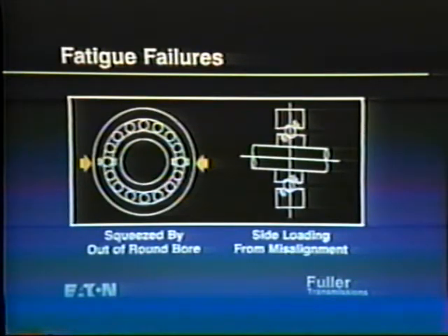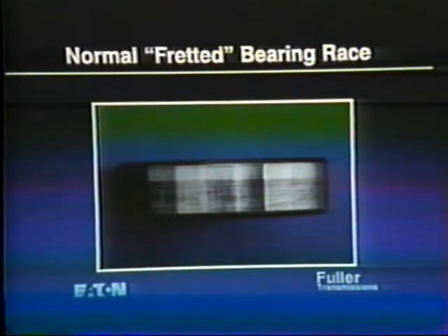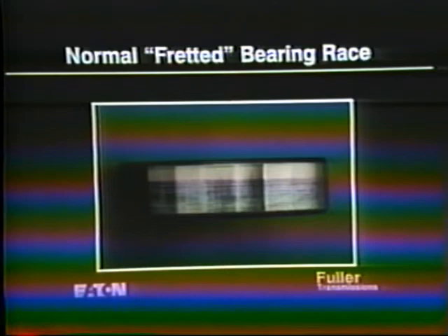Off-location bores will misalign the bearings, causing edge loading of the raceways. Never prick punch a bore to tighten the bearing fit. Bearing bores are sometimes re-sleeved because of fretting marks found around the outer bearing race. Often, the first assumption is that the bores are too large, allowing the bearing to spin. This is not the case.